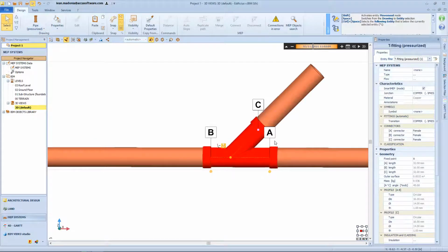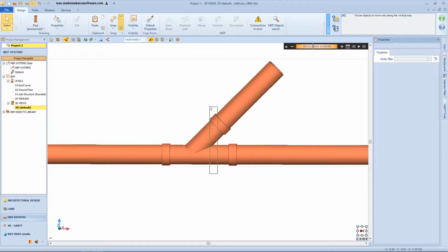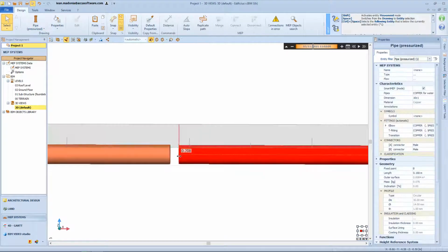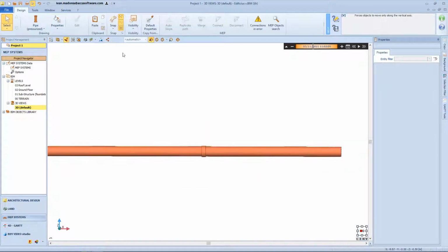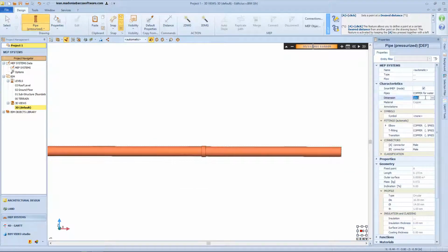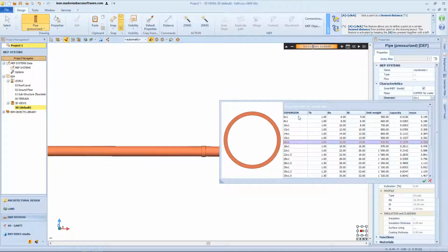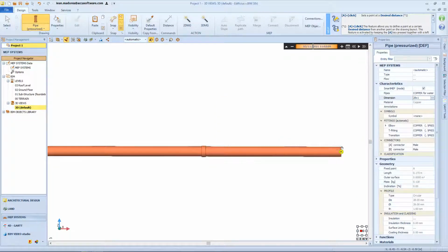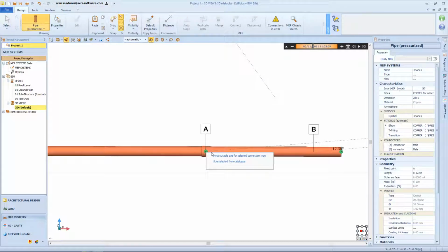If the profile has the same shape but different dimensions compared to the main pipe, the tube entity is activated and in the size field you can choose the dimension from the catalog or library, or, if necessary, you can configure a new dimension with the plus button. We intend a difference in size when this exceeds 5% or, in the case of very large dimensions, it exceeds 1 centimeter. In this case, a menu with two options appears in correspondence with the connection being made.